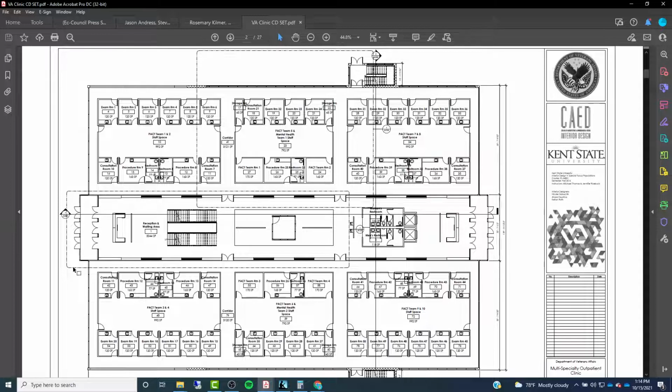Anytime you see one of these rectangular outlines around a portion of the plan, that is known as a callout. There's a tool in Revit for us to do this, but basically we're creating a reference for the person reading this to say, hey, if you want more information about this area of the floor plan, you're going to have to go to this particular page to see a blown up version of that area of the plan.